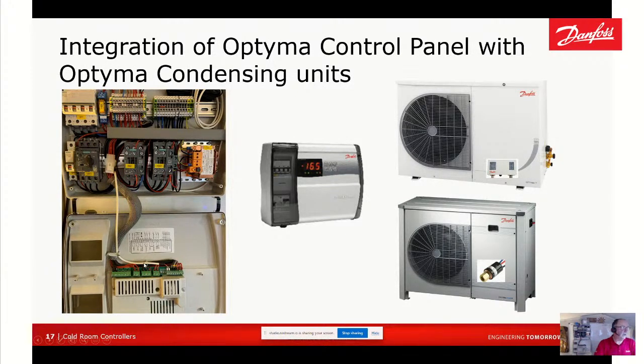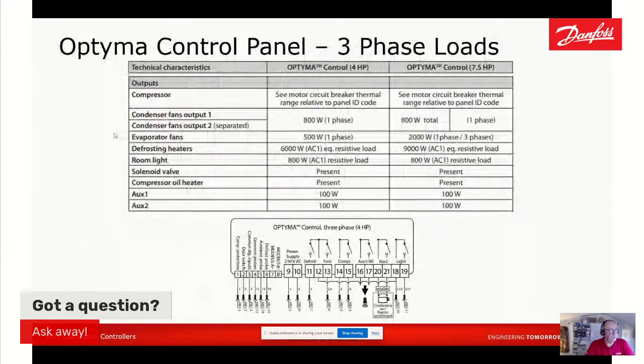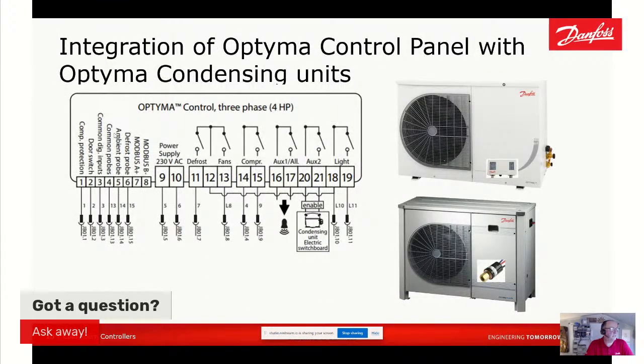We've got the relay card here, but because we're on a 3-phase version now, we've got contactors, motor protection, MCB, and there's a lot more load in there, so it pulls a lot more load. We're spreading that load across 3-phase much better, so there's a lot more components within a 3-phase panel than there is within a single phase panel. Okay, so we talked about that.